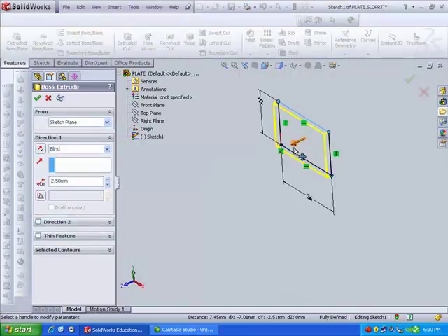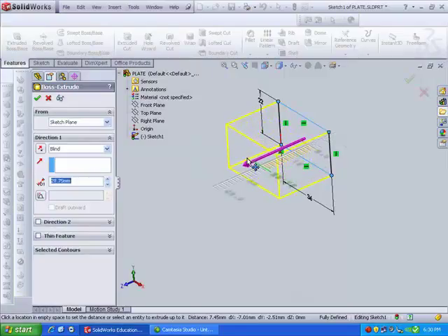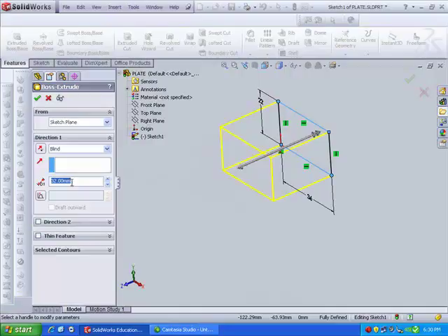Okay. Now you'll notice this little arrow here. You can actually grab that arrow, and a ruler imprint shows up. You can drag that, and you can see the feedback there in green. It's giving me the thickness. All right. See that? Or we can come over here and just add in our thickness. I believe our thickness is 5 millimeters.